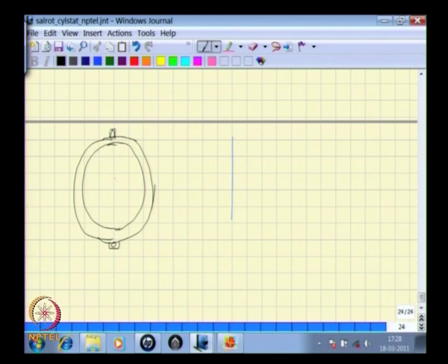If you have a cylindrical stator and a cylindrical rotor like this, you will find flux lines that are going to cross like this and come around. Similarly here, and one can now write the expression for Ampere's law around one of these loops.